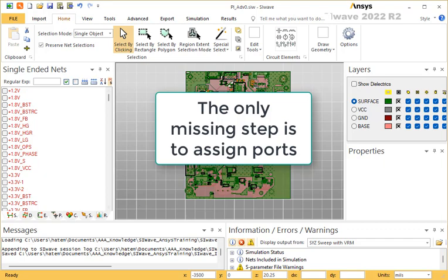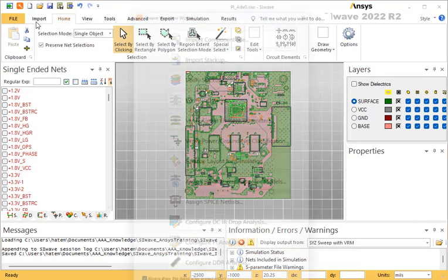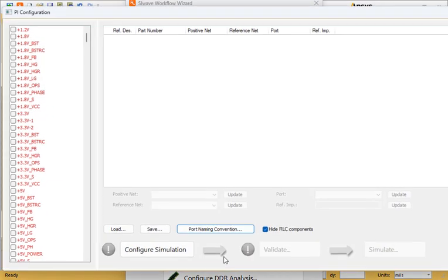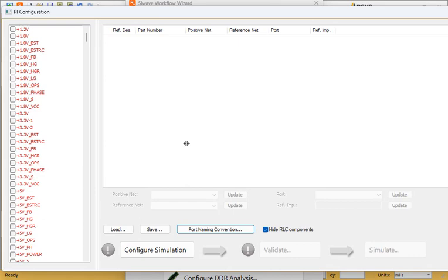That's all. So what you do, you click this button, you get the introductory panel, you click on PI, that's the one you want for a PI analysis. Now the good thing about SIwave is that when you want to do something, it starts by selecting the solver you want to use. And once you select the solver, immediately SIwave opens a dialog box.